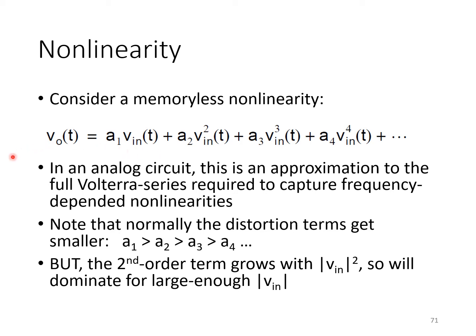In an analog circuit, this is an approximation to the full Volterra series required to capture frequency-dependent nonlinearities. A Volterra series is a nonlinear relationship between the output and both current and past values of the input voltage Vin. Such descriptions are complicated and preclude closed-form analysis in many cases. Moreover, this memoryless nonlinearity model will allow us to develop intuitions that are observed in practice, even in the presence